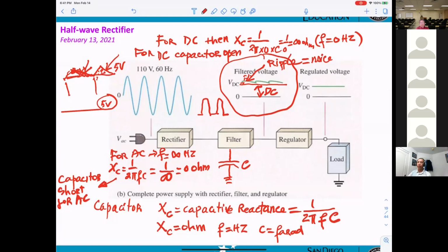Okay, if you want, you can run the simulation, to make sure you get straight DC voltage as much as you can. You can change the size of the capacitor, and you have to change the signal charging. That means the frequency will be high. So they charge and they try to discharge, and they just keep going. That will give you the straight DC voltage.